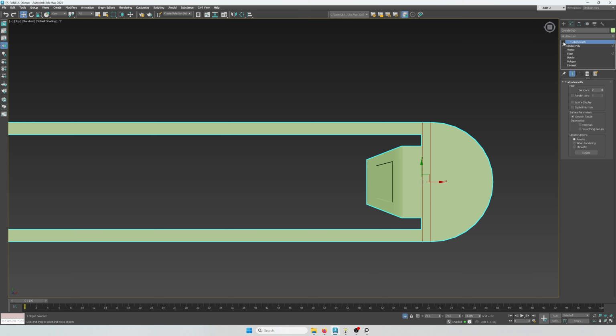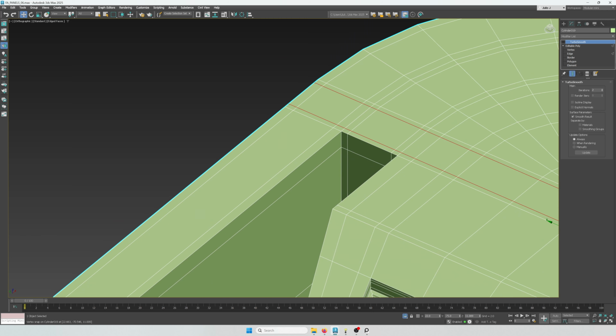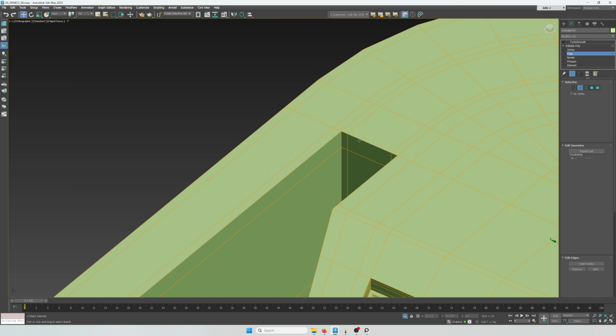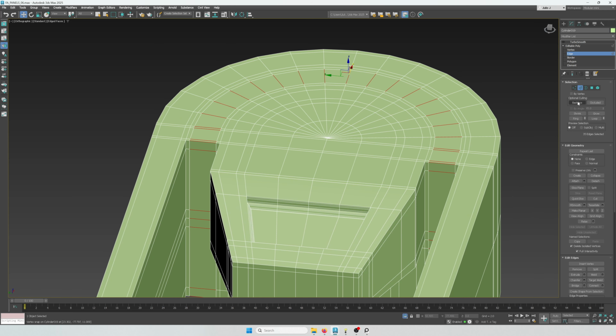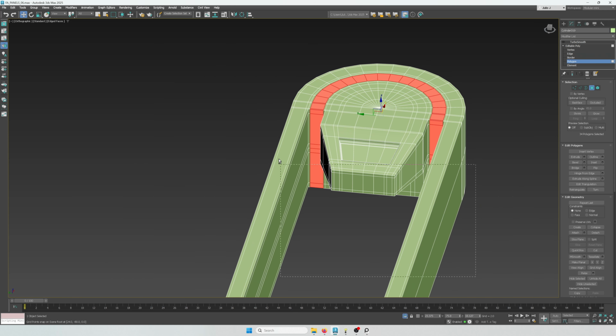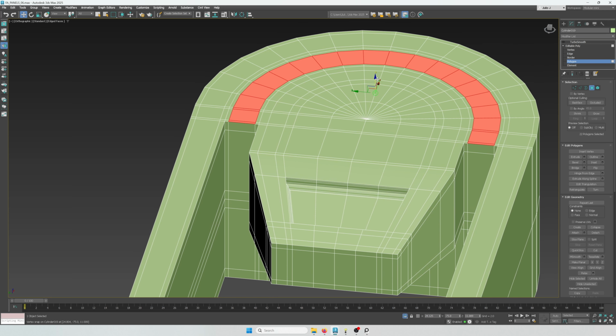Now I'm thinking about a circular detail that looks like it was drilled all the way around. So let's grab some of the top faces and extrude them down. I'm going to convert this edge selection into faces and then keep what I need. Holding shift, I'm moving them down while snapping on the nearest edge.